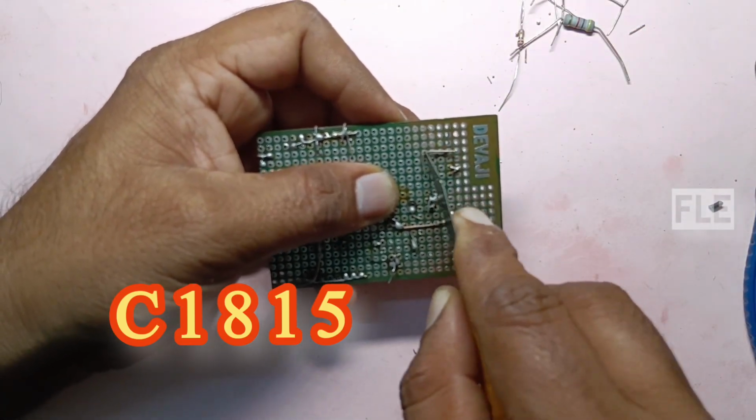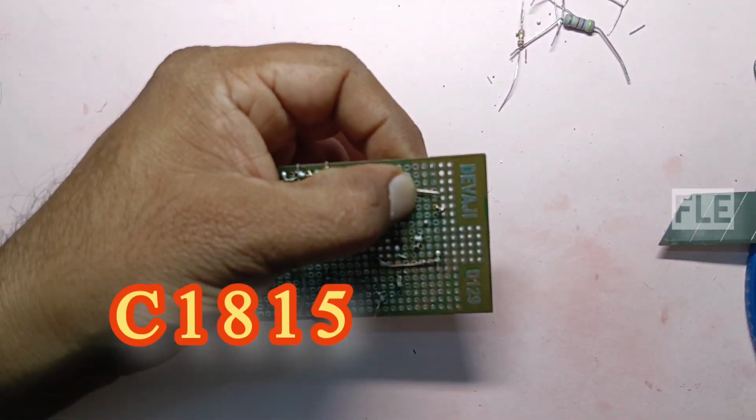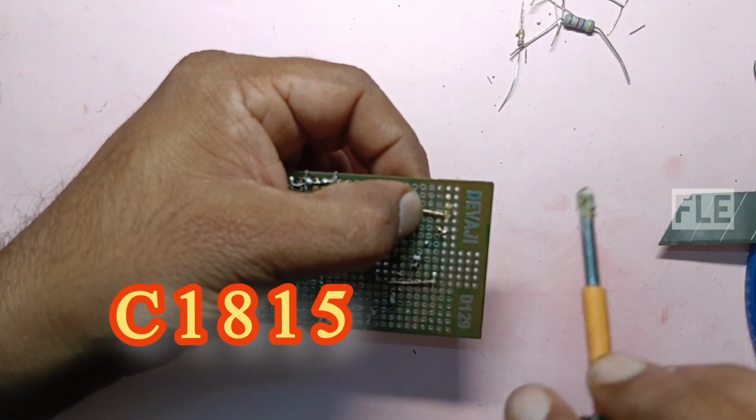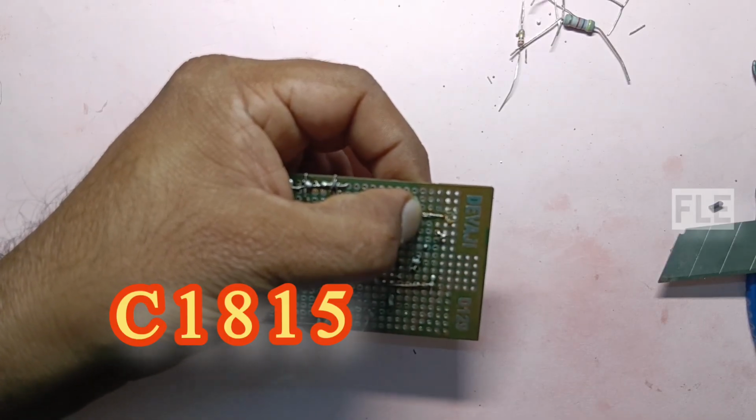Refer to the circuit diagram. Connect the 2.2 microfarad negative terminal to the base terminal of the C1815 transistor.